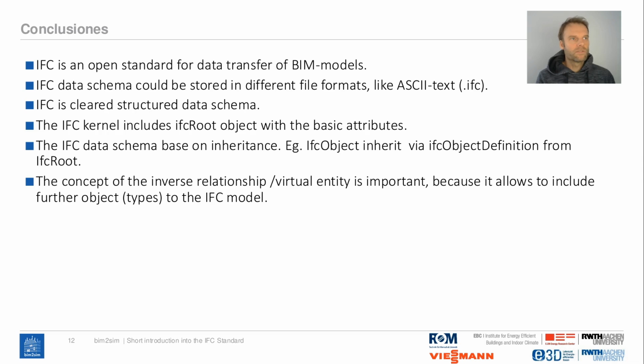The kernel includes the root object with basic attributes, and from this base, other objects on the lower level inherit the attributes. So a very important concept is inverse relationship or virtual entities, because it allows connecting further object types to the IFC model, like the IfcMaterial or something.